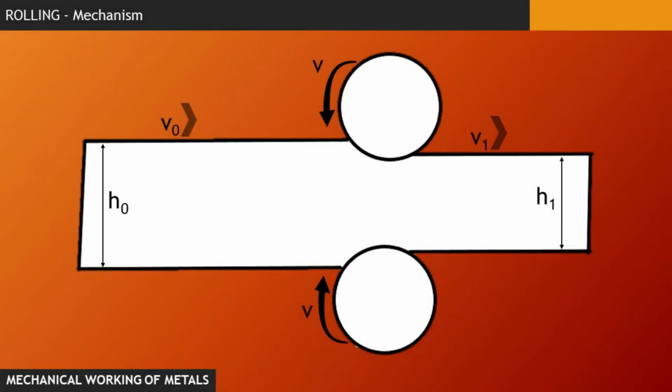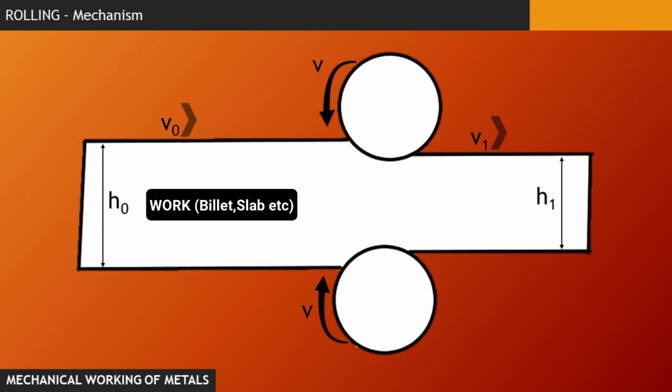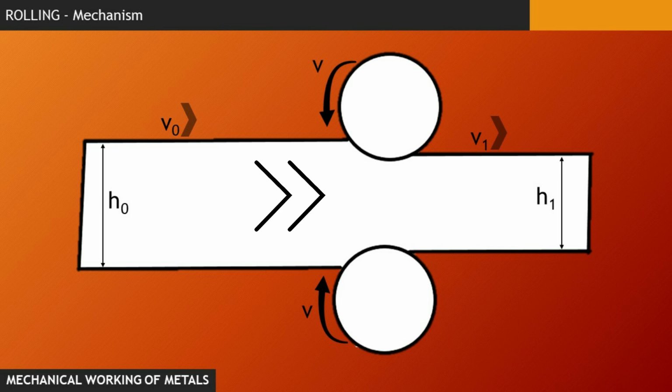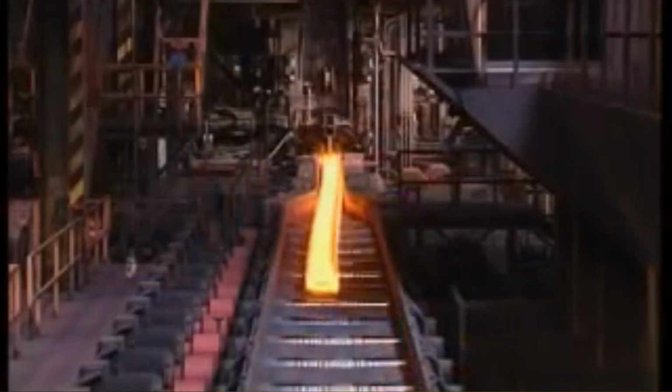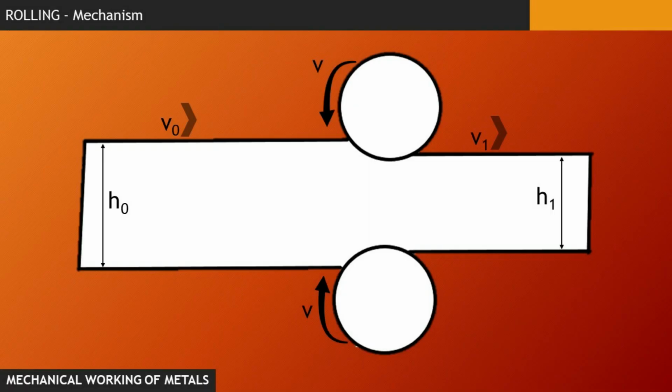In rolling, there are two basic components. First is the material which is being rolled, and second, the rollers which roll the material and perform the rolling operation. So let's say a material approaches two rolls. It approaches with its own velocity, which is provided by conveyor belts, and then under the influence of the rollers, it leaves with a separate velocity.